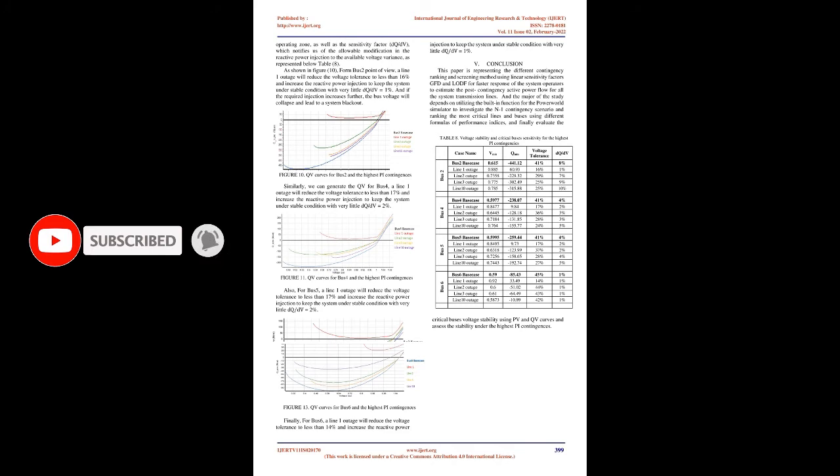As a result, for the different effects of the bus outages, when we monitor the transmission line power flow and calculate the active power performance index in Table 5, we conclude that the most severe outage occurred when the bus 2 substation got out of service with PI_MW equals 19.44 due to 3 line overloads, then bus 5 outage with PI_MW equals 13.77 due to 8 line overloads.